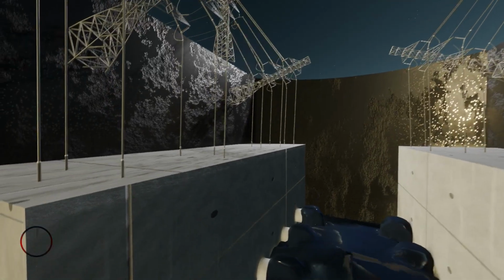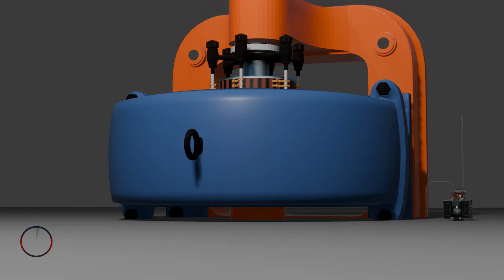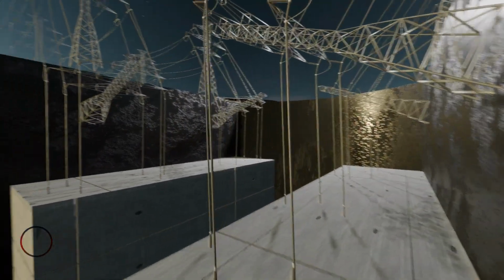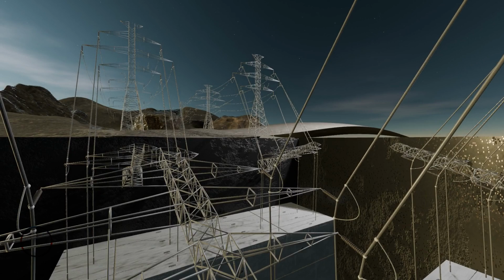In a generating station, the generated voltage is usually between 6 kV and 11 kV before it will be further stepped up to as high as 330 kV or more. The voltage range is a function of the grid rating voltage, so it can be more than 330 kV or less. The reason why the generated voltage coming from the synchronous generator is further stepped up is to prevent line losses, because the generated electricity will be transferred over a long distance before it reaches the grid for termination to the network.